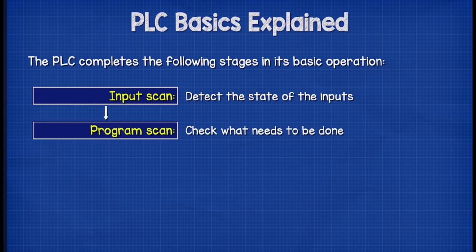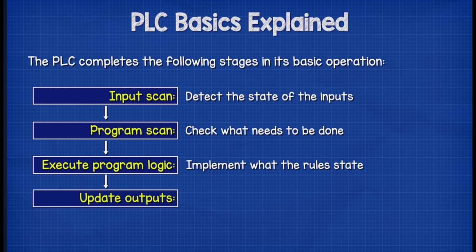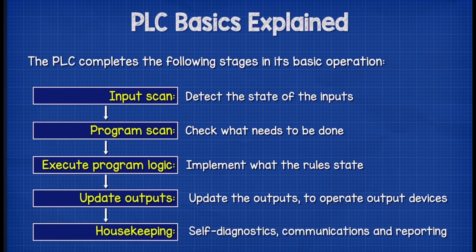Then the program scans to see what needs to be done. Then it will execute the program logic to actually implement what the rules state. Then it must update the outputs to operate output devices based on the program requirements. Finally, the housekeeping for self-diagnostic, communications update and reporting.